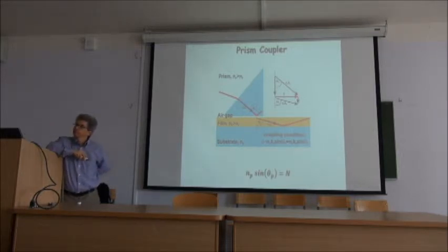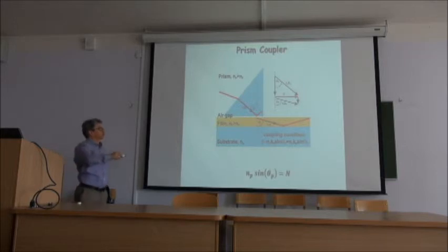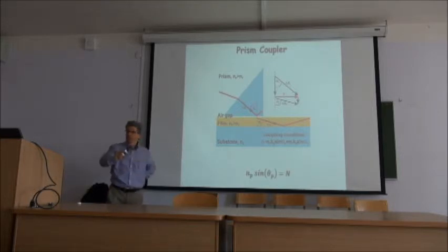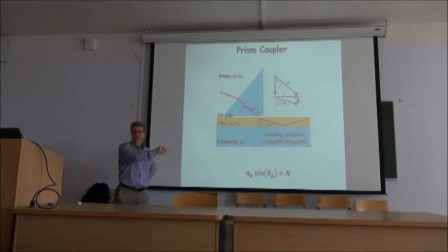The question is, what will happen if we change the air gap to a water gap or some other change? Yeah, so certainly you want this refractive index here to still allow guiding. That's a must. You don't want to put anything here that has a high refractive index, otherwise the light will decay extremely fast.